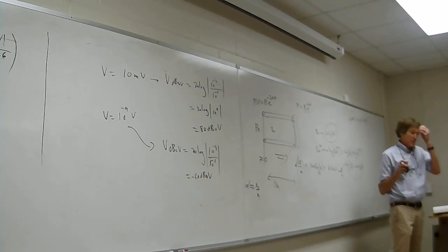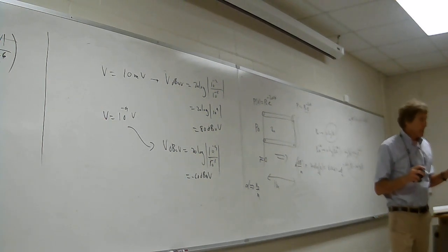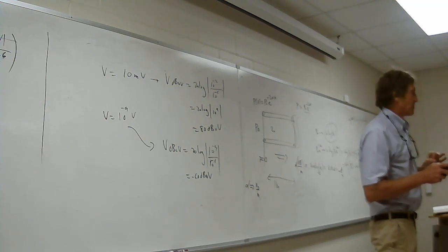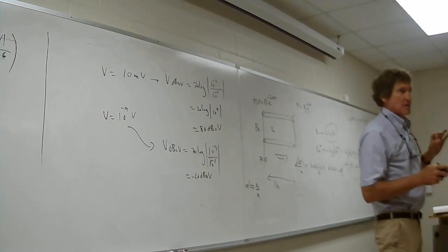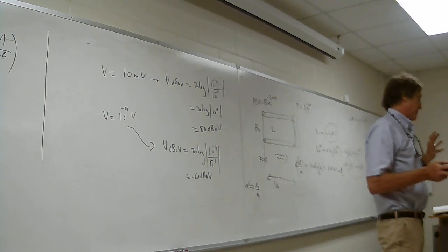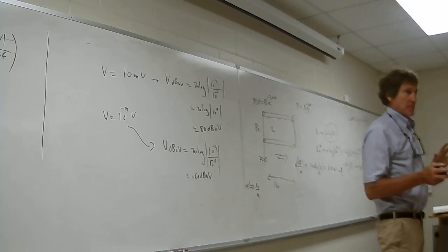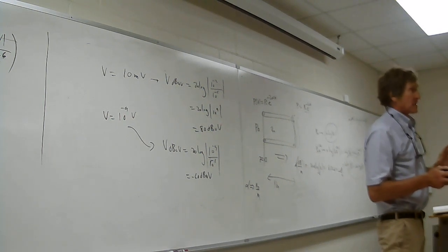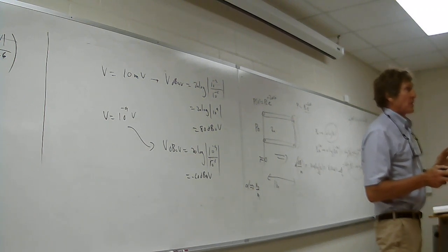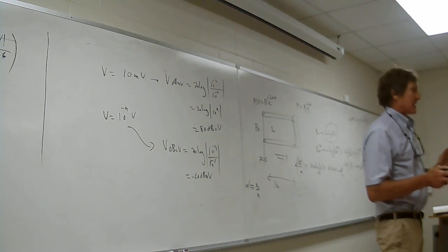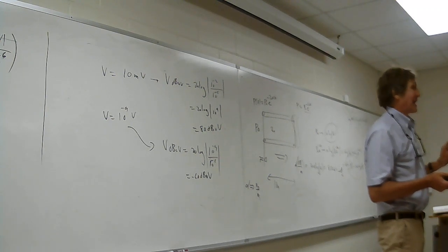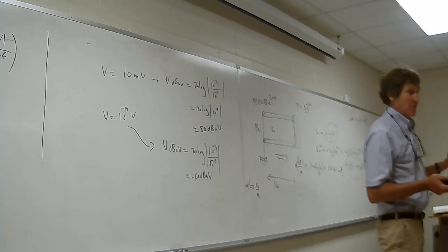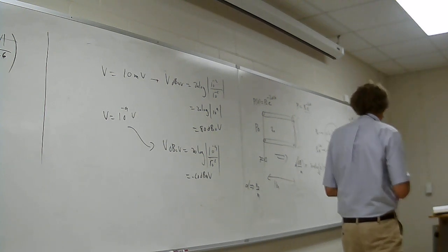Normally, have you all looked at like coax cables? You know, they'll have a certain attenuation dB per meter. It's real important to understand that. Usually it's dB per hundreds of meters. Typically 4.5 dB per 100 meters, which is not bad, but that's standard for, what is it, RG58 coax. When you have fiber optics, it's almost nothing. It's like maybe 0.1, 0.2 dB per mile. And that's the reason they use that stuff. Almost no attenuation. There's dispersion, but not much attenuation.